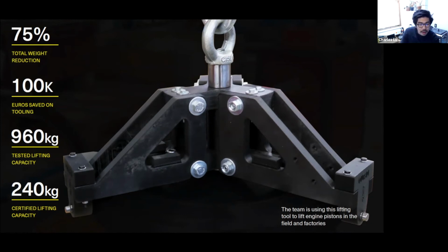Cyclical loading. That's actually a great question. I think based on light cyclical loading, it depends on the duty too, right? So if you're going for very light duty, kind of like vibratory wiggle, I would say that it's probably fine. If you start doing really big oscillations, that in any carbon fiber composite could cause delamination. So that's something to consider, the duty at which you're doing that. We also have different materials which are built.